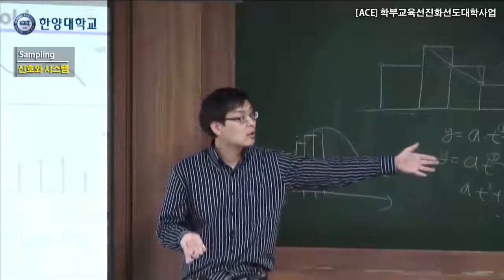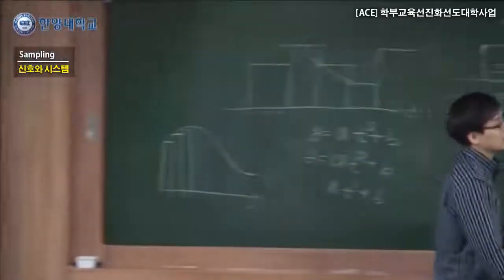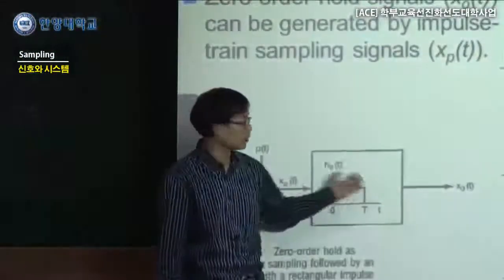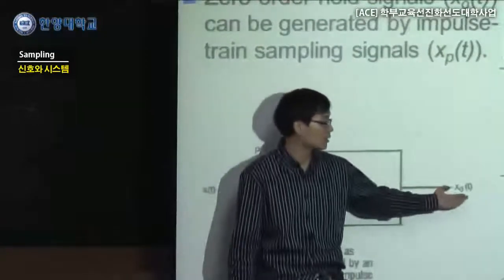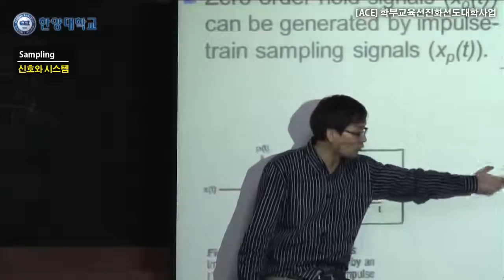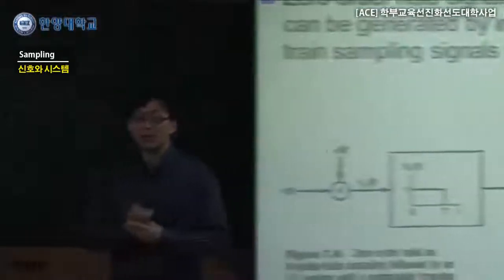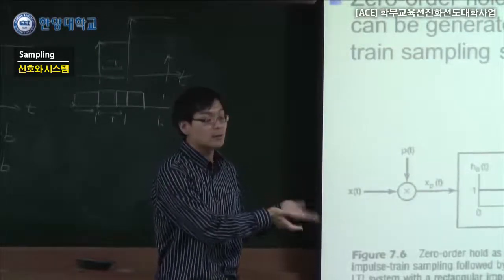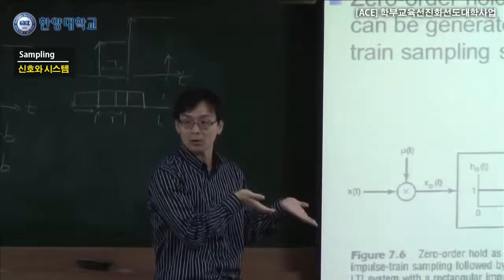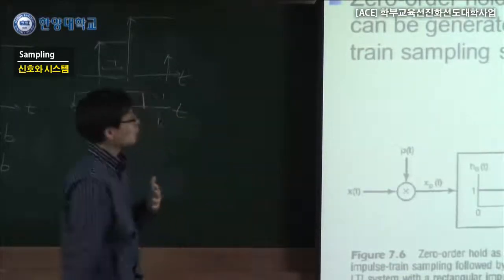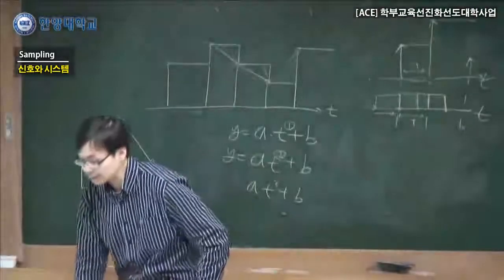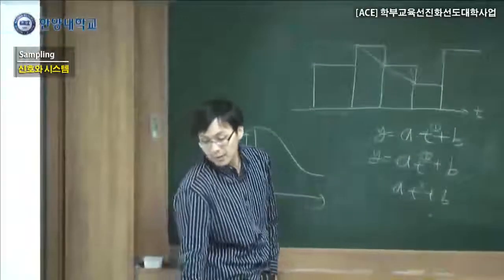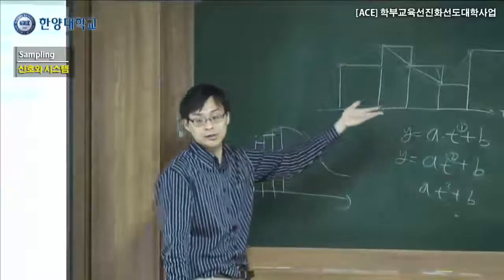One example is we implement a new system in this box holding for a certain t, and when the discrete time signal passes through, it becomes a continuous time signal, which is not really the smooth thing we expect to have, but one of the good estimates. This may be enough. If you don't like it, if you need a more accurate value, you should increase the order. One way you can increase the order here is you can either connect them using a straight line or connect them using a round line, which is a higher order system.